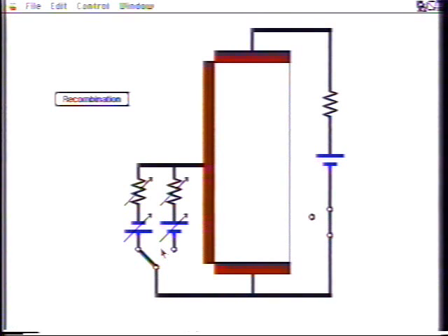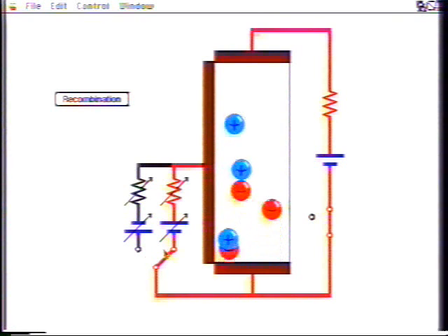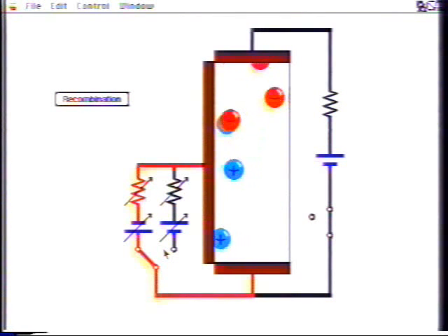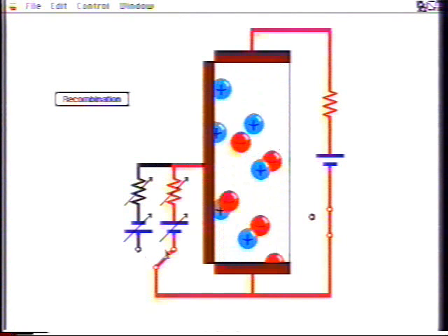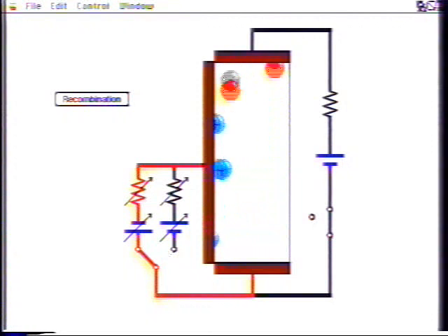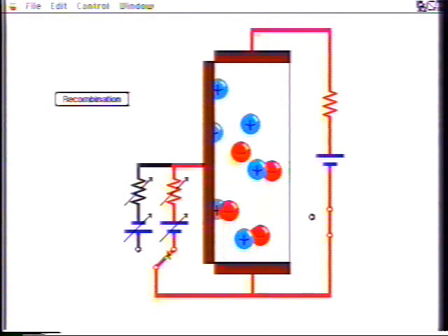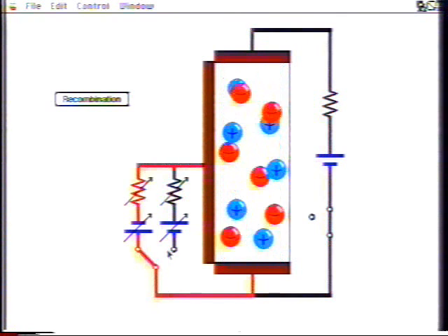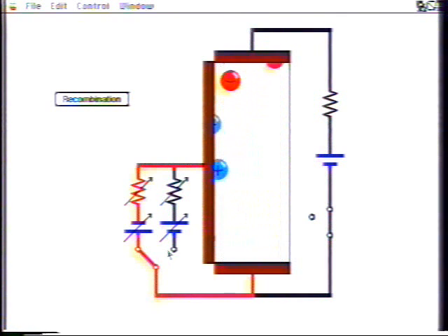The basic operation of the BJT is exactly like the FET. Output current is controlled by input charge. Input current only flows when the controlling charge is being changed. Externally, the base emitter terminals behave as a capacitance, known as the storage or diffusion capacitance. Positive base current charges up the diffusion capacitance, turning the collector switch on. Negative base current discharges the diffusion capacitance, turning the collector switch off.